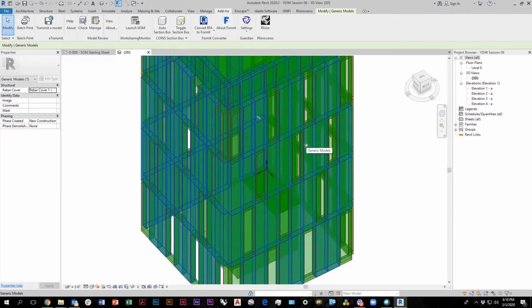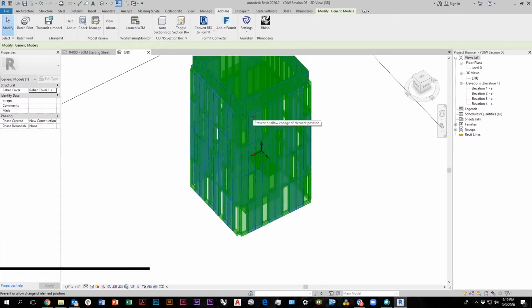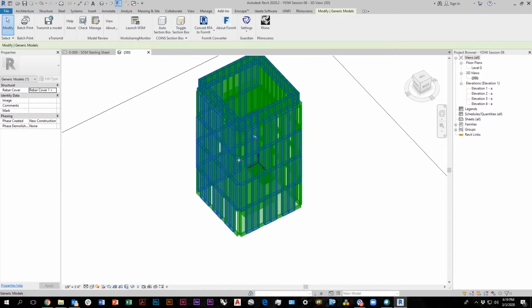And you can turn that Rhino geometry into Revit geometry. So you can add in the walls and actually specify what those walls are. So you can do the documentation together, but you can model in the program you'd prefer modeling in, which of course is Rhino. Because modeling in Revit, it sucks so bad, but it's so powerful. So this is kind of a happy medium between the two.